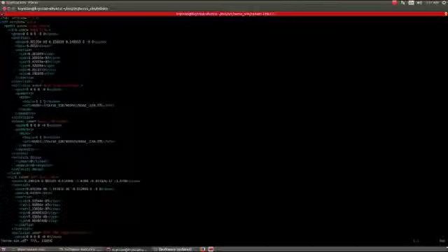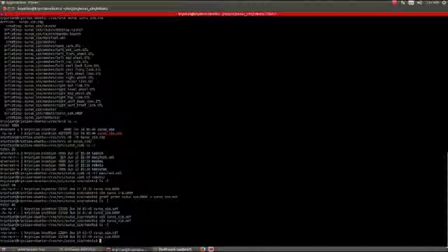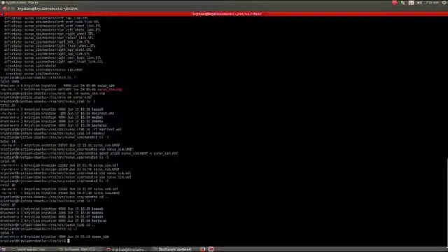So I just want to show you one thing. Now that we pretty much have the file in SDF format, what we can do is simply view how this exported mesh or exported robot is going to show up in its current state in Gazebo. So what we will want to do now is copy this entire sudo sim folder, and place it into the home folder in the .gazebo models folder.